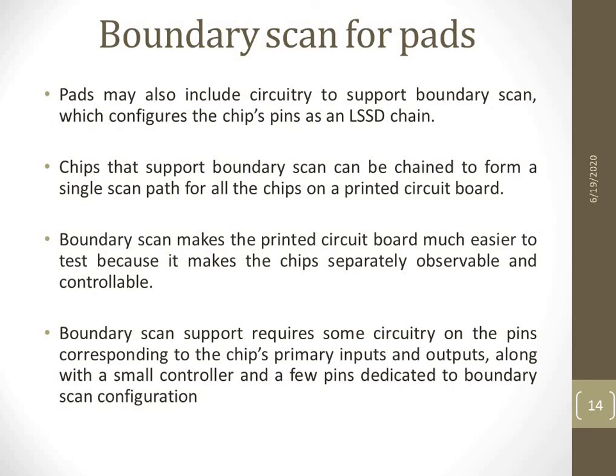Then for these IO pads, if they are separate, like only input pad and only output pad, what are the problems? And we have seen the three-state pad circuitry. The three-state pad, with the input mode, can be made to act as an input pad or an output pad, or only as high impedance. That is called a three-state pad. And we have seen how to use these pads for boundary scan. Boundary scan is important for testability, or testing the chip.